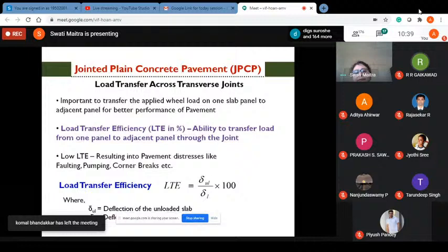And the pavement quality concrete is M35 to M40. So the grade of concrete we generally use is M35 to M40. M40 is the standard thing. That means the compressive strength is 40 megapascal.